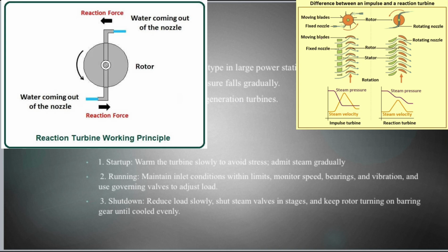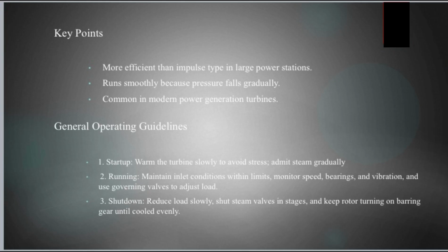The steam turbine cannot be shut down suddenly; we must reduce load first, then shut the steam valves in stages, then keep the rotor turning until it cools down gradually.